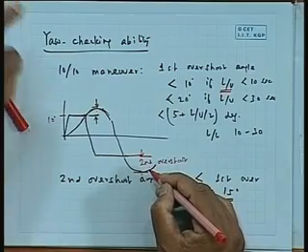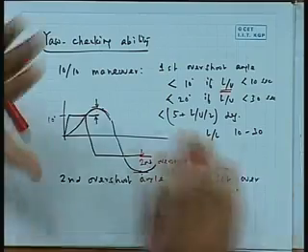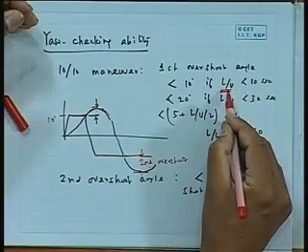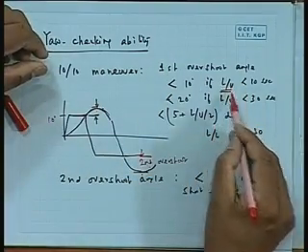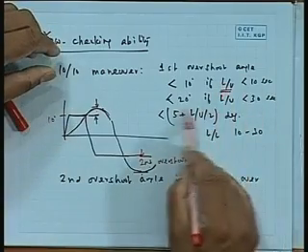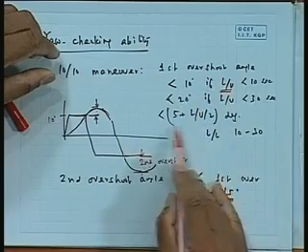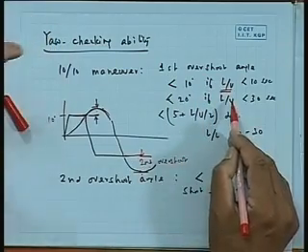Second of all, you wanted this overshoot angle to be somewhat connected to length and velocity. Longer ships should be allowed more overshoot angle. This L by V parameter is there, and you can make out from there that the first overshoot will be 10 degrees, etc.